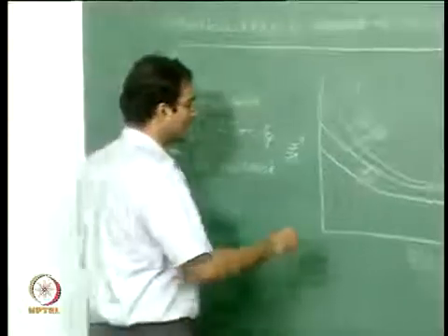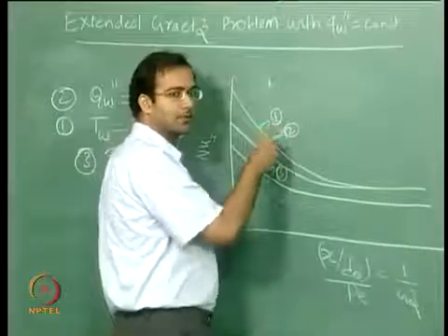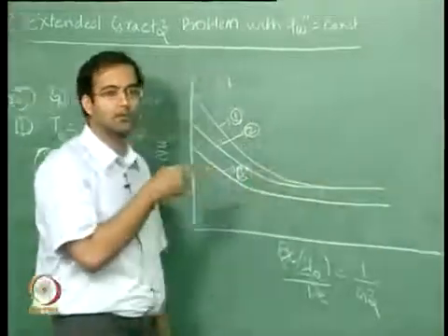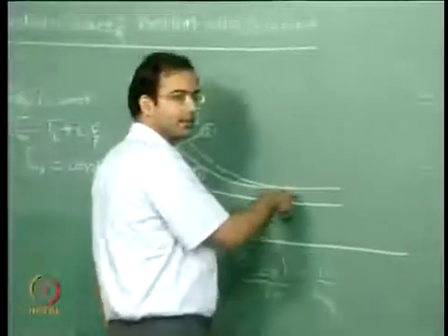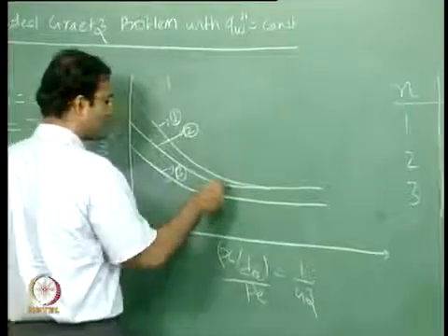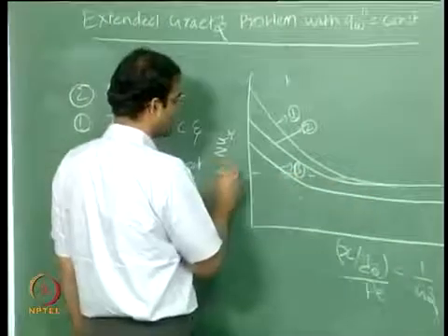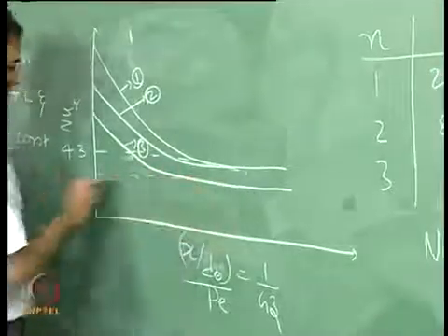Okay. So finally, whether it is linear variation of wall temperature or Q wall is a constant, once it becomes both thermally and hydrodynamically fully developed, they reach the same value. That's why these two merge, and you see the corresponding value is 4.3, and for the wall temperature you have 3.6.